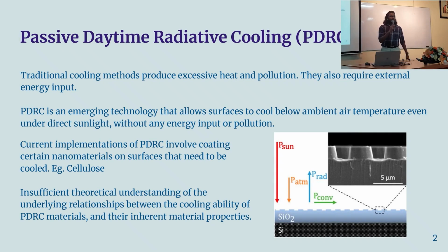The problem with traditional cooling methods, such as air conditioning, is that you need energy input for the technology to function, and it also produces heat and pollution. To address this, PDRC, or passive daytime radiative cooling, is proposed as an emerging technology which allows surfaces to cool below the ambient air temperature.